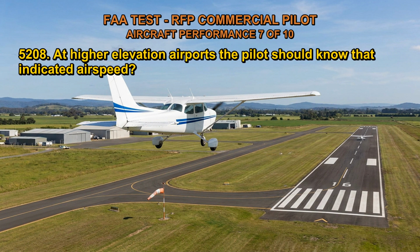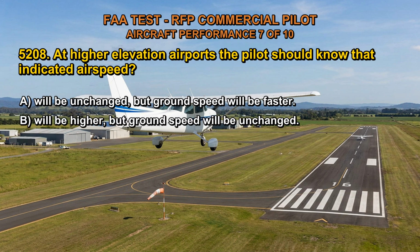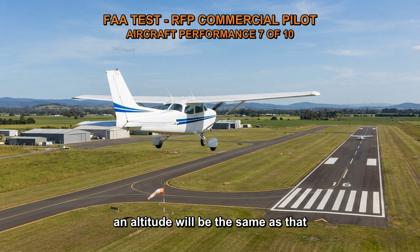5208. At higher elevation airports, the pilot should know that indicated airspeed A. will be unchanged, but ground speed will be faster. B. will be higher, but ground speed will be unchanged. C. should be increased to compensate for the thinner air. The correct answer is A. The indicated airspeed of an aircraft landing at altitude will be the same as that at sea level, but the true airspeed will be higher due to the lower air density. The ground speed will be higher if the true airspeed is higher.